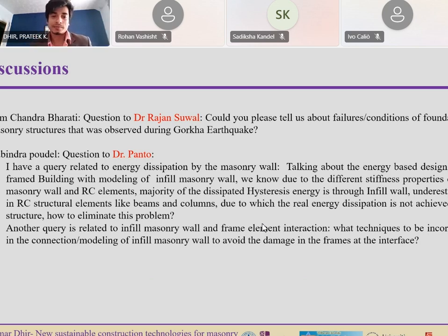This is very important. Visiting many parts of Kathmandu, we saw a lot of reinforced concrete structures. We also have many of these in Europe. Unfortunately, many times these buildings are designed or assessed just neglecting the influence of the infills, and the results that we get are sometimes very unrealistic.